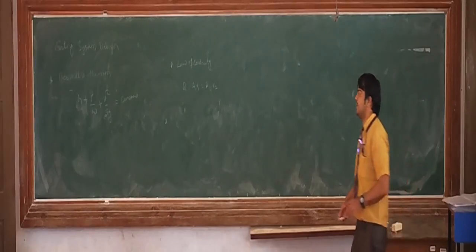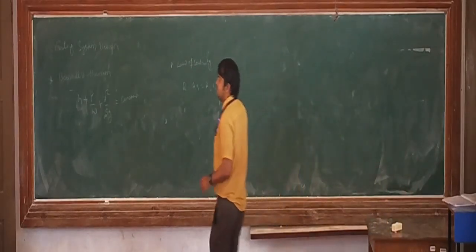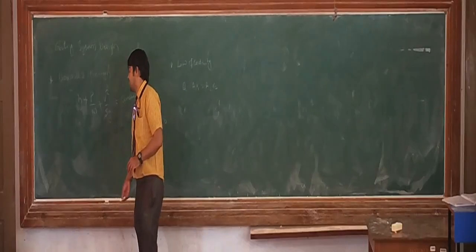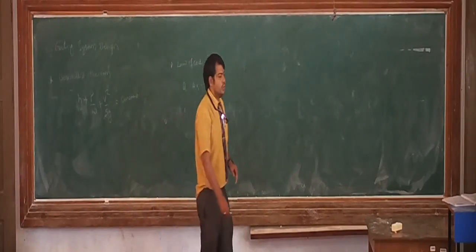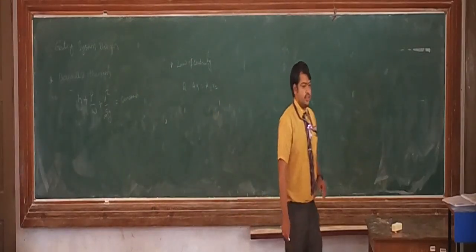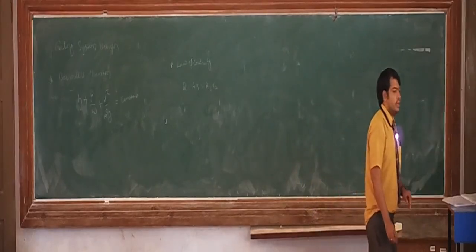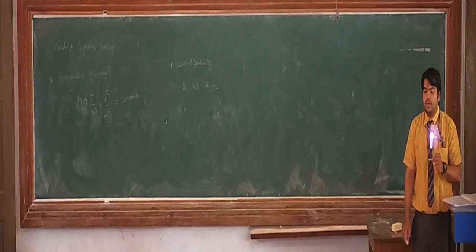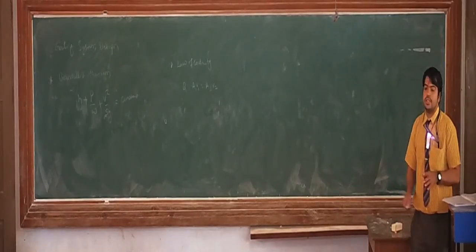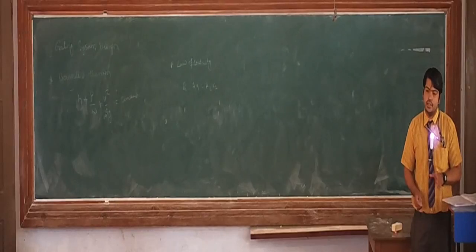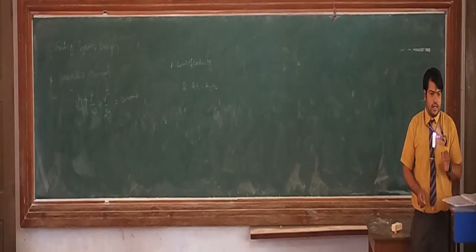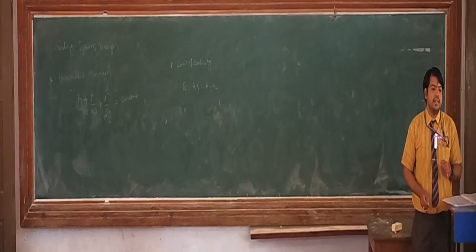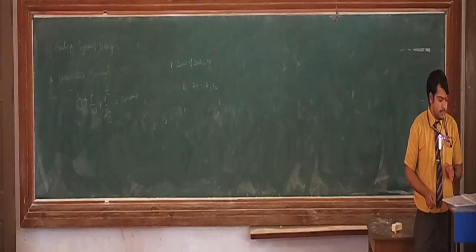Mathematically it is generally denoted by H + P/W + V²/2G = constant. Whereas the law of continuity states that the flow of metal, or the rate of discharge, is going to remain constant at any given cross section in the mold cavity. Understand this, the molten metal acts as a fluid. That is why the laws of fluid mechanics hold good for this molten metal.